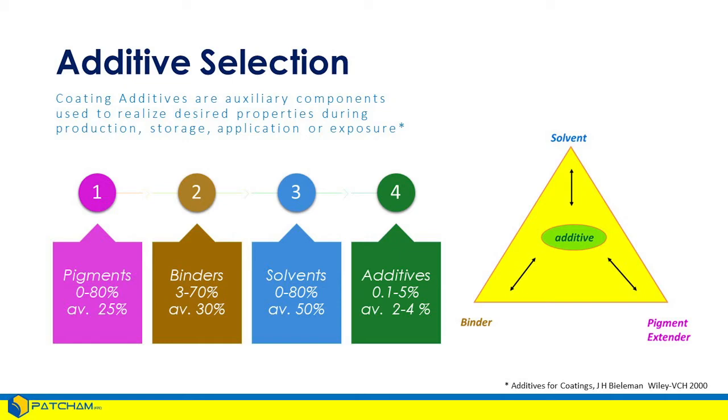Second, binder. We want to protect the substrate. Well, that's what the binder's function is. The binder is selected and designed to cover the substrate, hold these pigment particles as individual particulates while it's protecting the substrate. Third, the liquid solvent, which we use to put the binders into a liquid form.